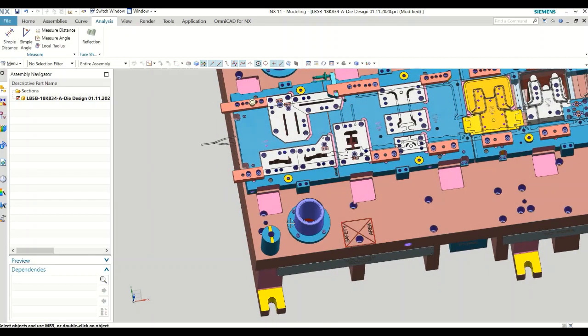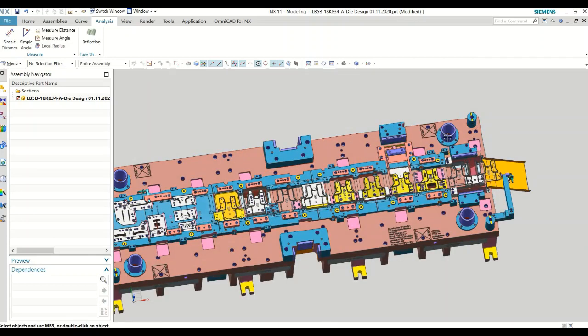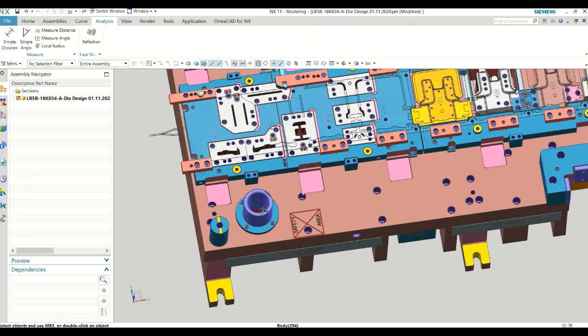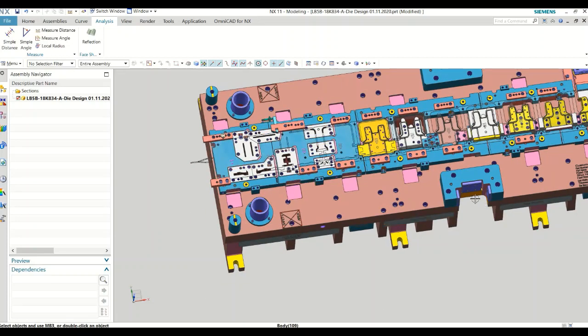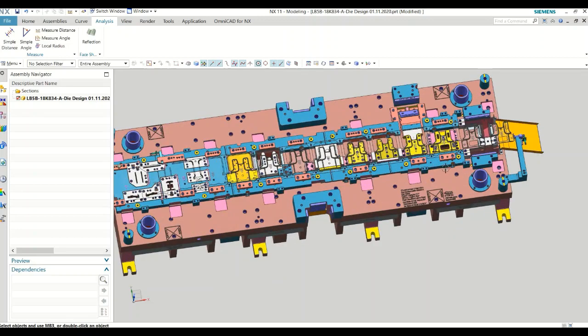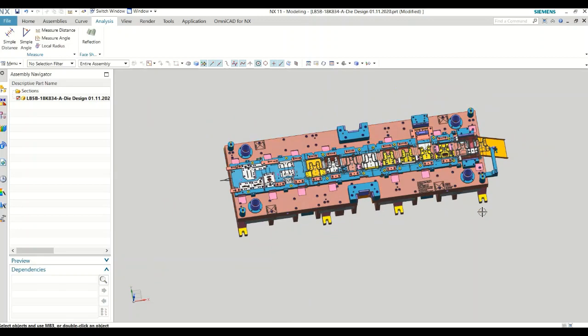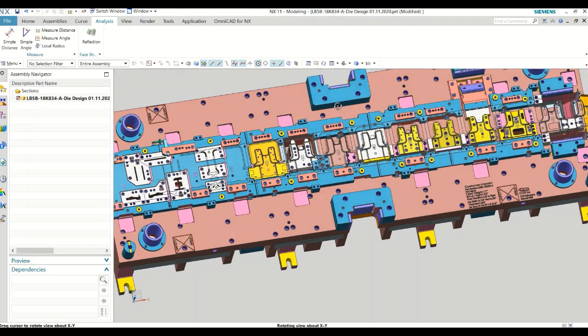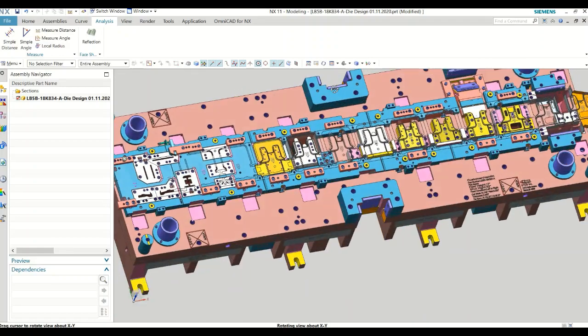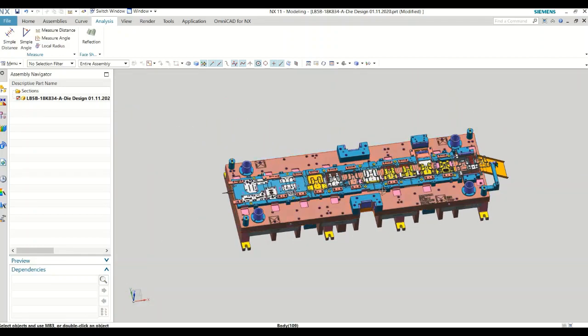And these four, it's easy for you to understand. These four are nothing but guide pins and guide bushes, guide bushes for the upper die. To control the forces, we have these two lower guide blocks. We have a guide post in the upper which comes down, and that is the way we balance out the thrust because of the shape of the part.